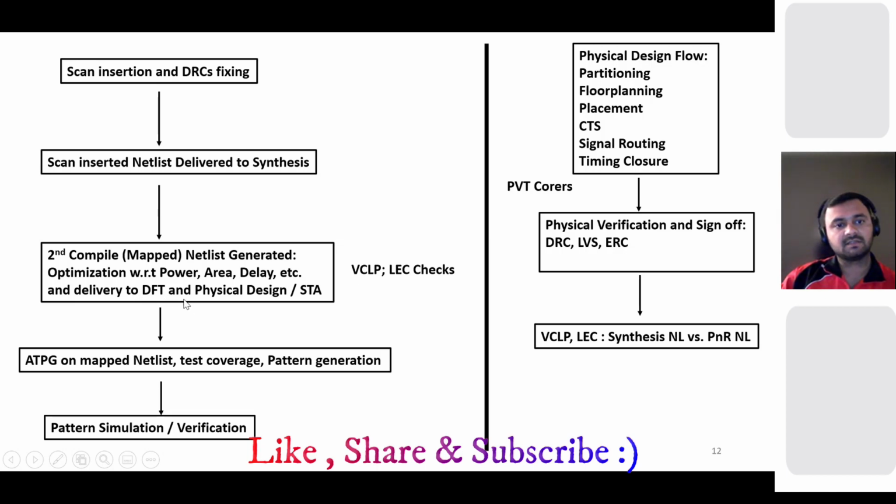Then again, they will give the mapped netlist to the DFT team. So then you will perform the ATPG on the mapped netlist. You will focus on the test coverage, how many faults you can detect on your chip, and you will generate the pattern and simulate it.